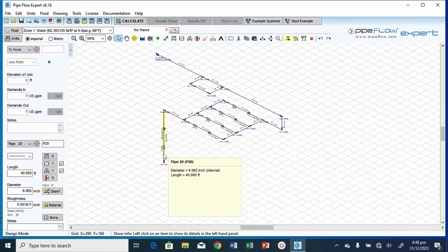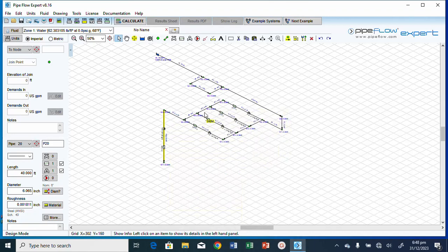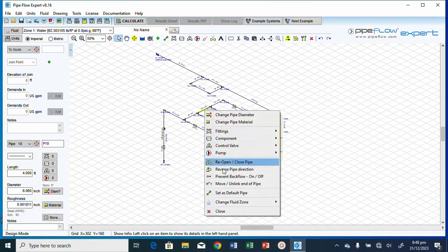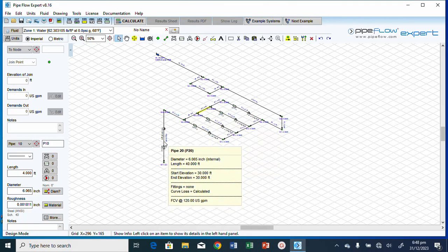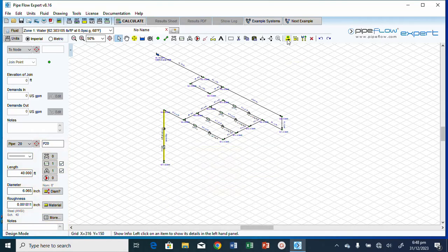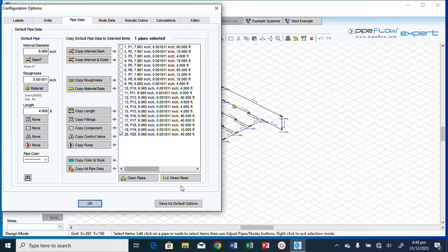Okay, I didn't change the attributes. So I need to change the default pipe value attribute. For me to do that, I'll select this, right click, set this plain pipe that does not have any fitting as the default attribute. Say yes. This is 4 inch. So I'll select this button, select this, then change it to the default attribute.